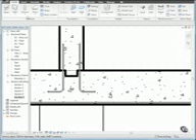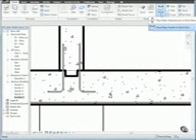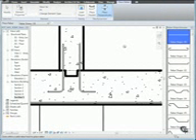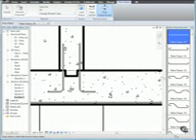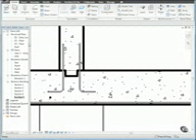On the Home tab, from the Reinforcement panel, click the Rebar drop-down and select Place Rebar Perpendicular to Work Plane. Then, click the Change Element Type drop-down and select Rebar Bar number 8. Then, click a point between the hooked and straight bar approximately as shown. Then, click Modify, and let's place rebar set.